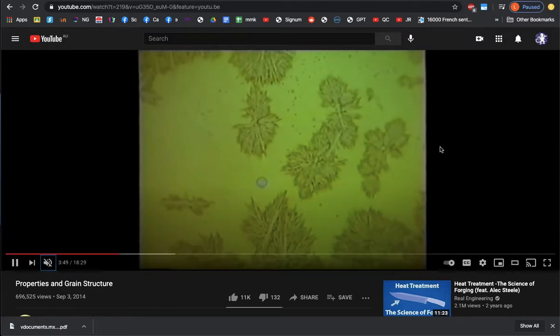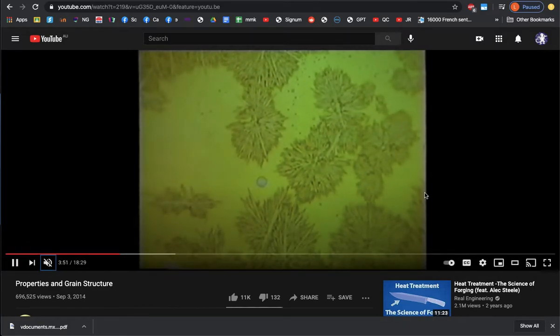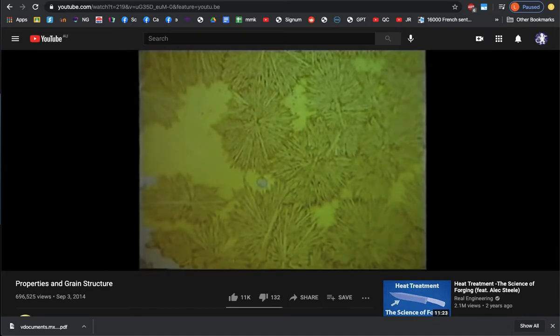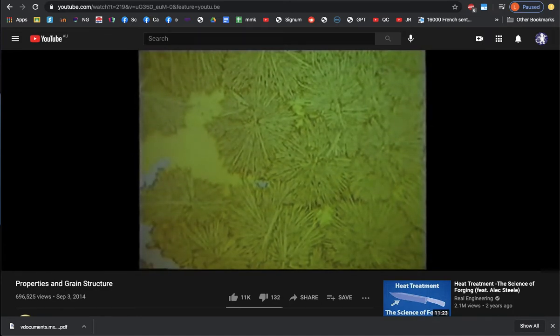So we've got nucleation points. They then form into dendrites. Dendrite is Latin for little tree, and they look a little bit like little trees. And then we often get secondary branching. In this case, we can't really see as much secondary branching, but we can see some grains starting to meet, and we have a grain boundary forming at those points where the grains are starting to meet. There's a grain boundary. And the grains keep growing. As they cool, more and more atoms are joining into the crystal lattice until eventually the thing is complete.